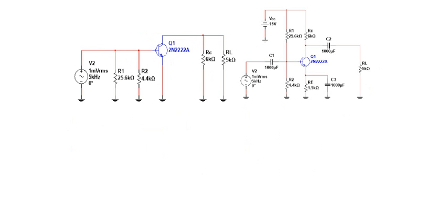Now, I'm not going to worry about R1 and R2 for the moment. I want to talk a little more about the right-hand side of the circuit. There is an internal resistance to the transistor, to the emitter portion of the resistor for AC only. And we use lowercase letters for some of the R's that we're going to deal with here that are just for AC only. We call this one little RE prime.